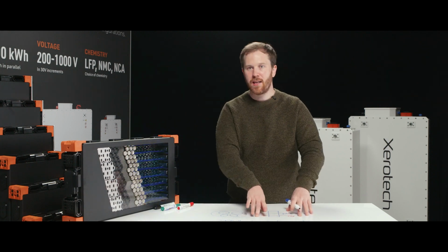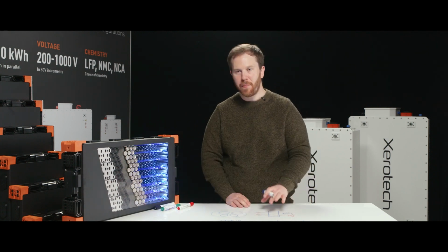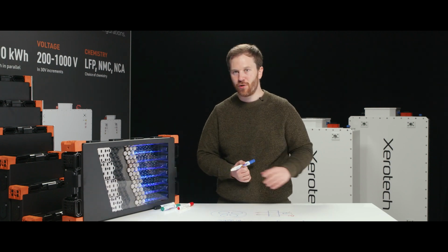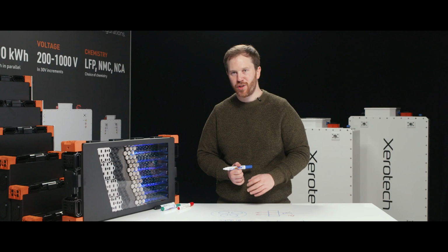So that's directly cooling the battery cells. It can be an effective way, especially with direct immersion cooling or direct liquid cooling, but the challenges there are more practical of heavier solutions. Your dielectrics have lower thermal performance in some cases, and obviously leakages of the whole battery pack system because you have many more leak points in place.